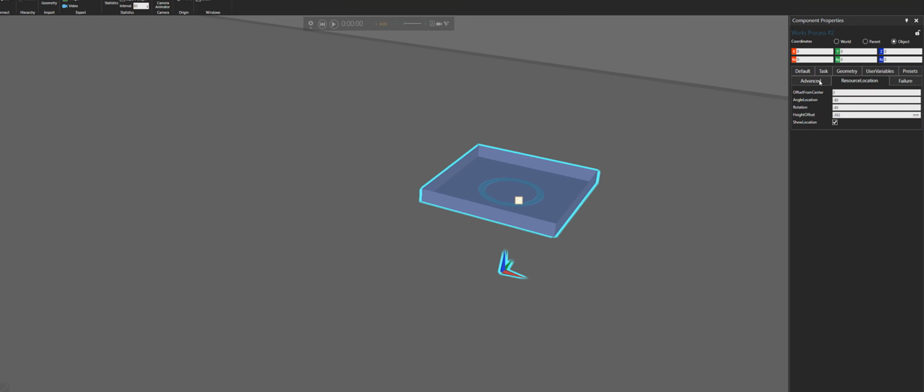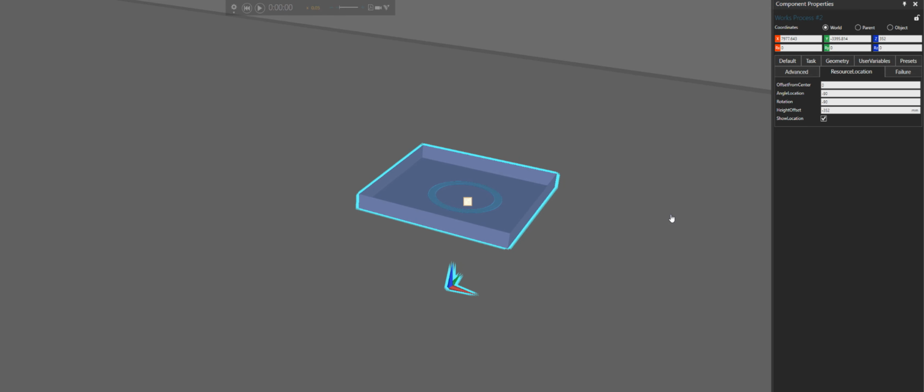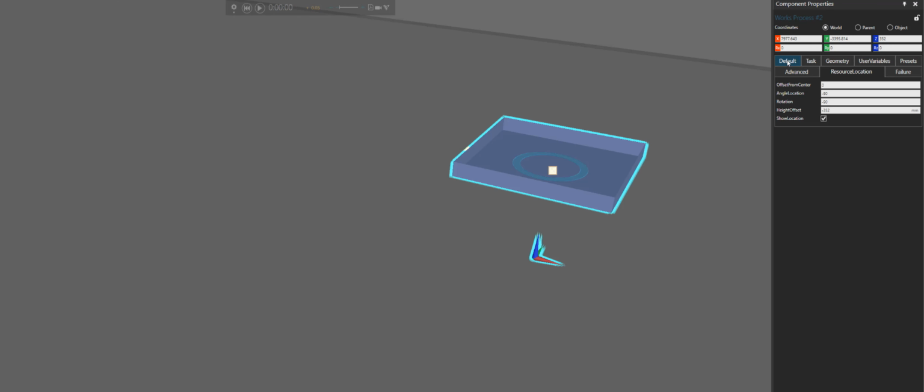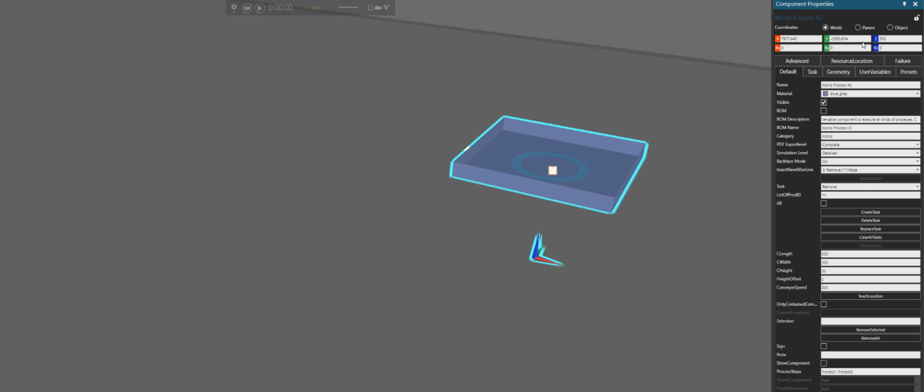of the component itself. So if I go back to the world coordinate system at this station here, go to its default tab, you can see its height right now. The component is 352 millimeters in the z-axis. I base this, of course, on the specifications for the MiR100 robot. And if you check, its height offset property here is 0. So we're not elevating it above the floor with some offset here, we're elevating the component.